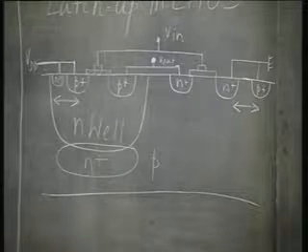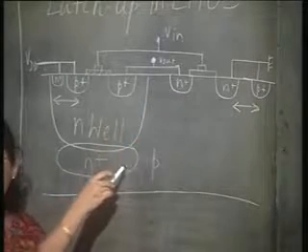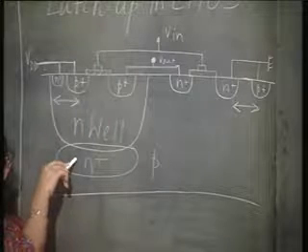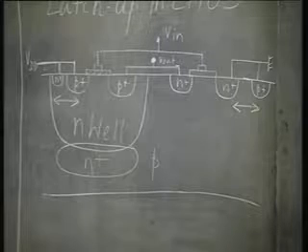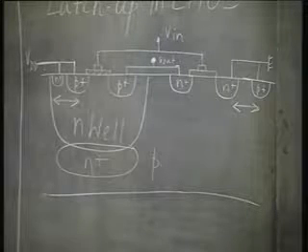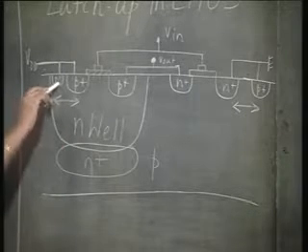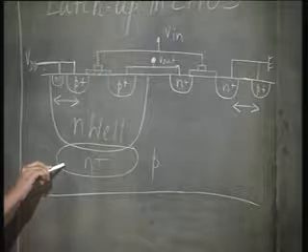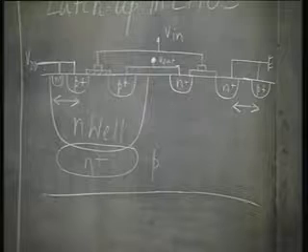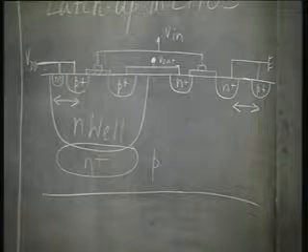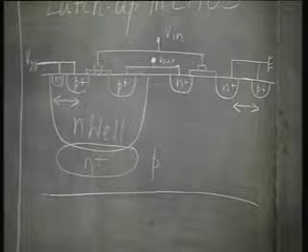Okay. Again you see you are achieving the same thing, because when electrons are injected from here, it is actually flowing through this N plus region where it encounters very little resistance. There is no question of having a sufficient voltage drop to turn on this PN junction, right. You can have this N plus extend all the way to this N plus, so as to cut down the shunt resistance by a large extent. So, there is going to be no question of any regenerative feedback.